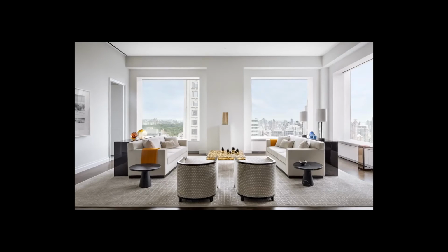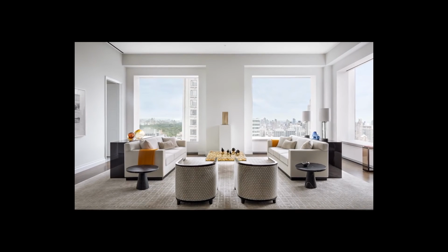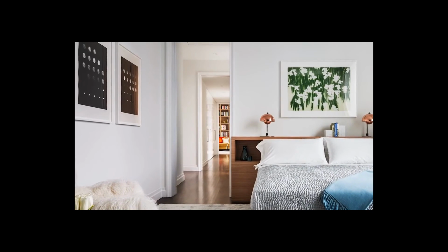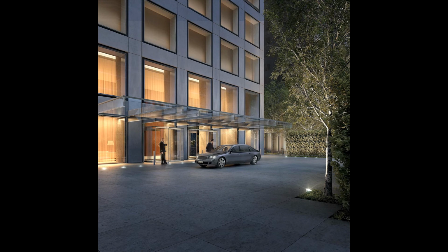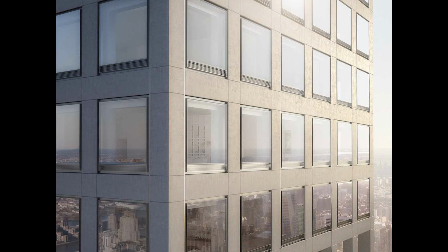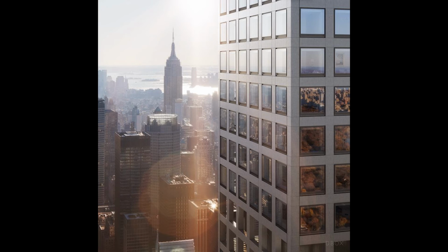432 Park Avenue set out with the aim of creating luxury apartments with incredible views of New York City. The large feature windows, the column-free spaces, and the tall nature of the building have all contributed to the building's success in this area. Being such a new tower, if there are any problems, they are unlikely to have become apparent already. One issue could be with the fair-faced concrete facade. Without proper maintenance, staining could ruin the appearance of the tower.